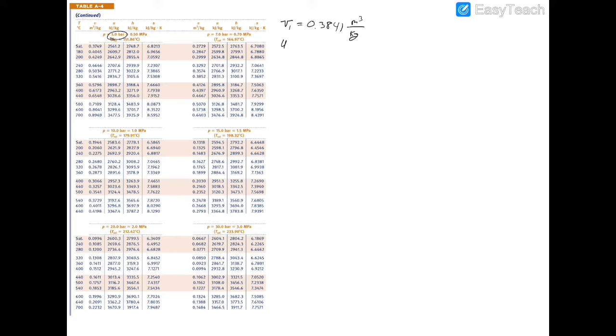And the change in internal energy, I should say, the specific internal energy, is going to be 2576.5 kilojoules per kilogram. I personally chose to interpolate underneath 180 and 200. You could have also interpolated from the saturation temperature at 180, and you would have taken the in-between value.